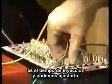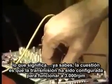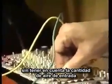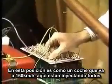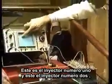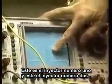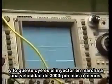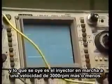Good. That means now we know the engine is specifically being set, because of the transmission, to run around 3,000 RPM. That's good. Regardless of the year that we're going to be in. Now that's like the car running about 100 miles an hour. You'll notice here that this pulse is the inject. This is the first injector, and then that's the second injector. And what you're seeing here and the sound that you're hearing is actually the injectors operating at that speed. Now if you're going about 3,000 RPM, I expect it to be something like that.